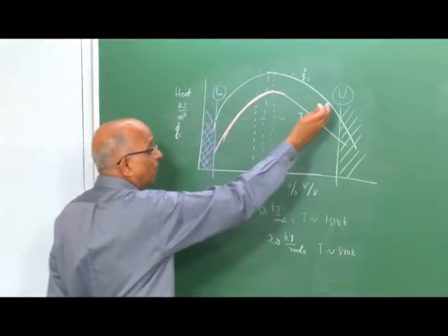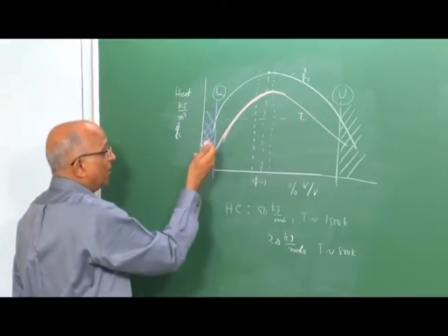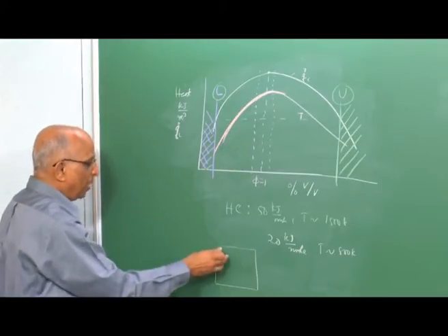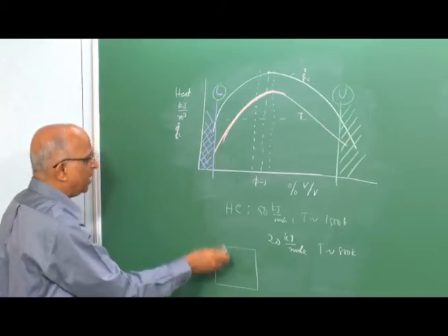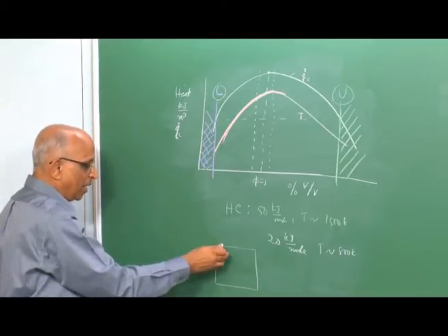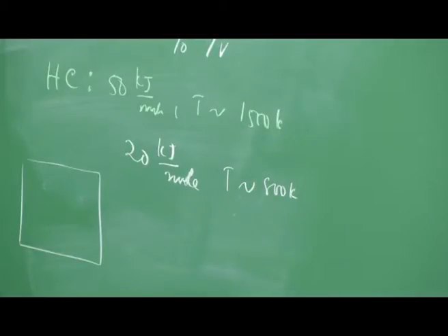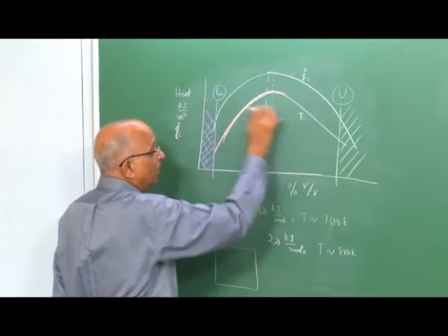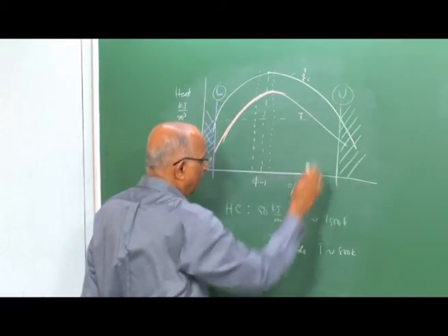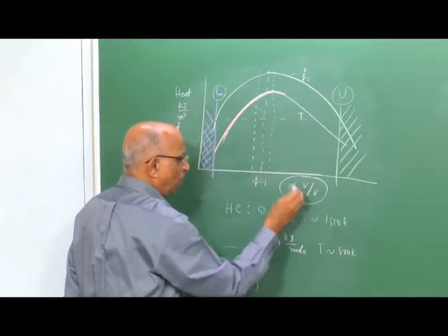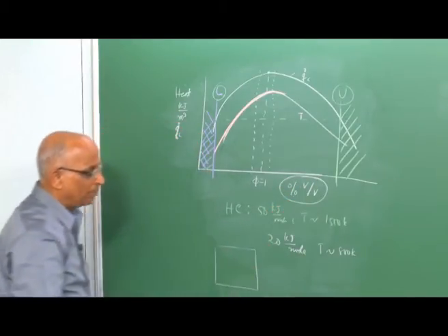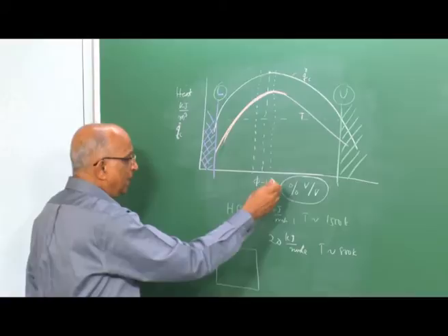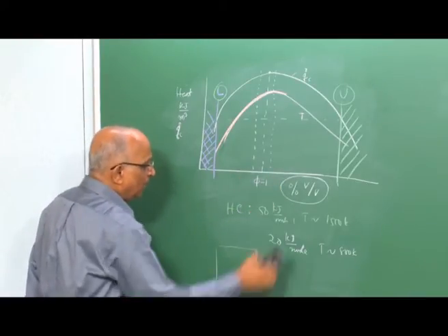But L and U are very strong parameters, because if I have, let us say, an explosive gas mixture that could explode, maybe I could sort of inert it and make it weak such that it is in this region, and I am able to handle an explosive safely. And this is an important parameter. Therefore, we say L is the lean limit of flammability and U is the upper limit of flammability, and it is specified in percentage volume of fuel divided by the volume of the mixture.